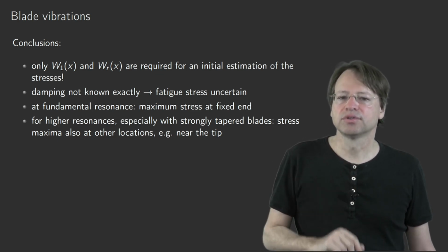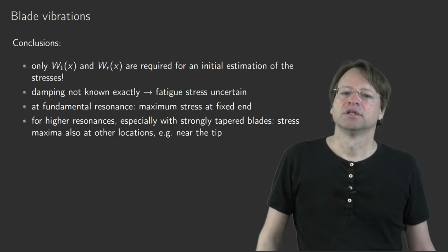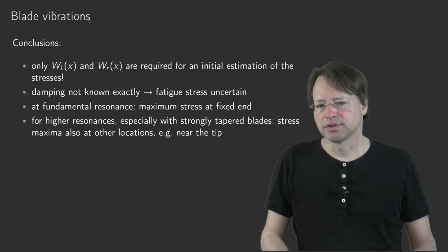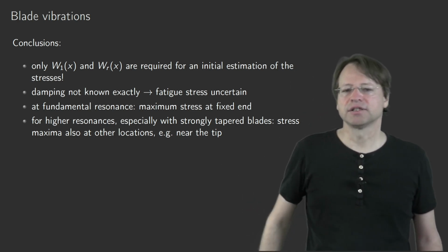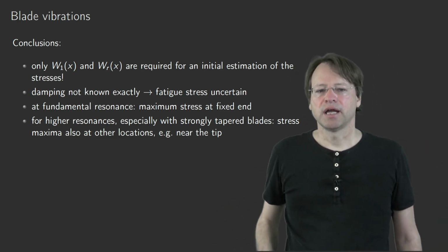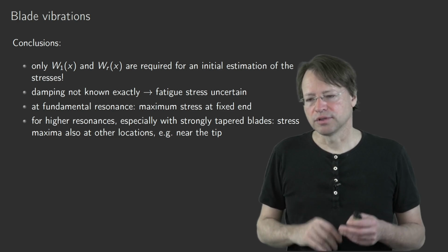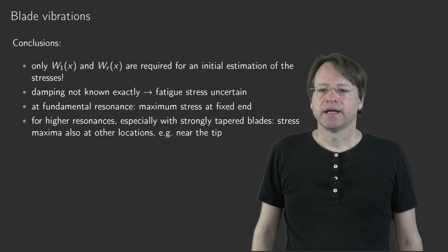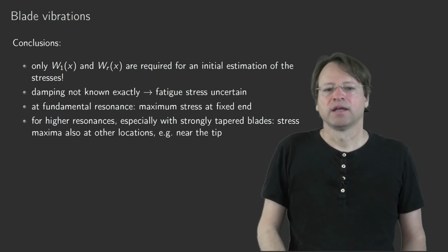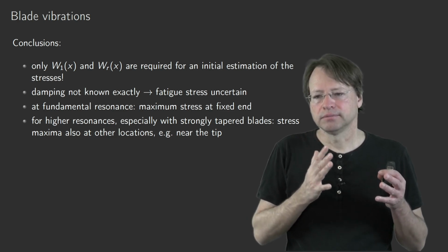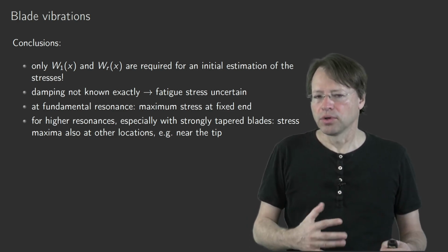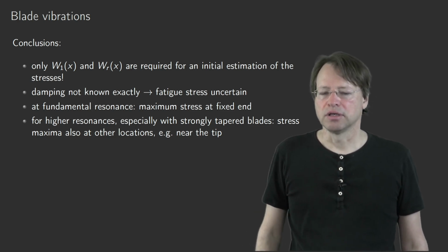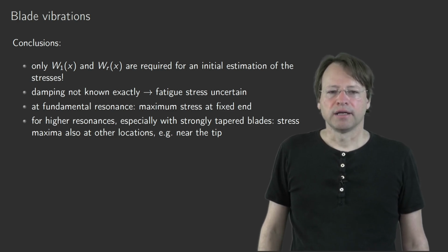So you have to try to reduce them as much by doing very, very good simulations that take possible disturbances that represent classical manufacturing disturbances and disturbances or uncertainties in the geometry coming also from operation into account, trying to classify where higher loads might occur, and such a detailed analysis allows you then to reduce the safety factors.